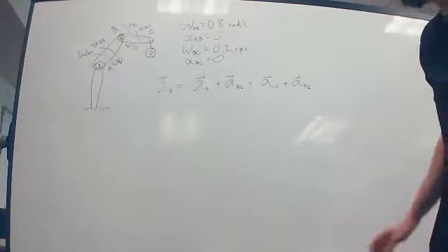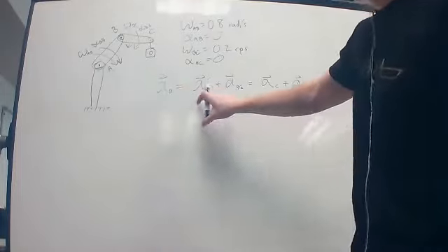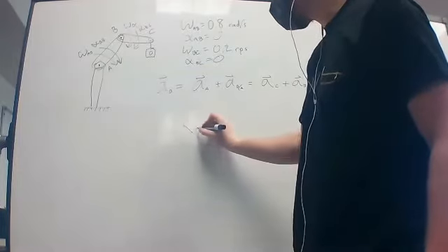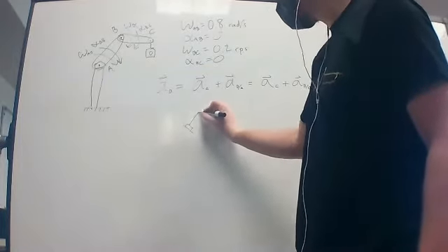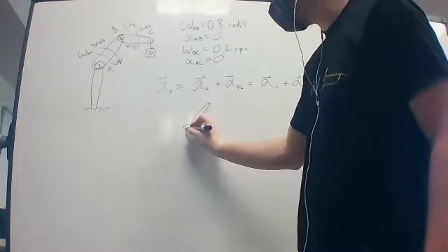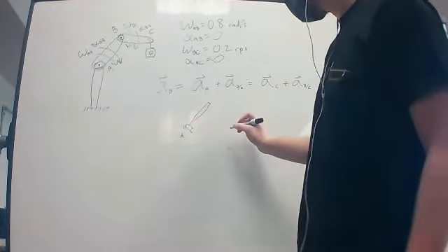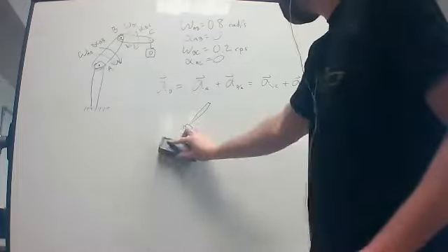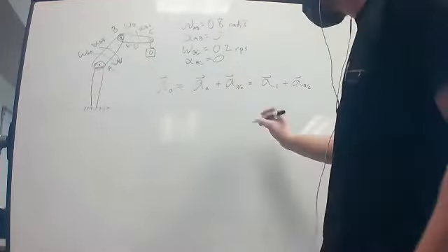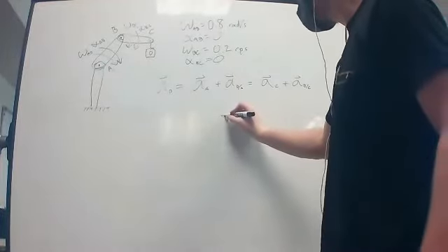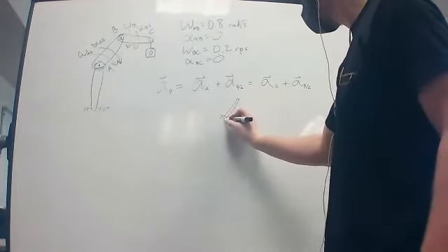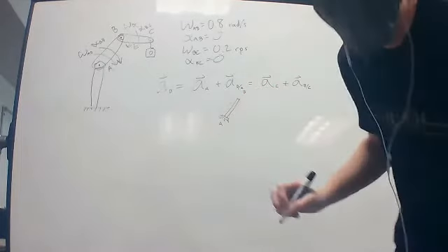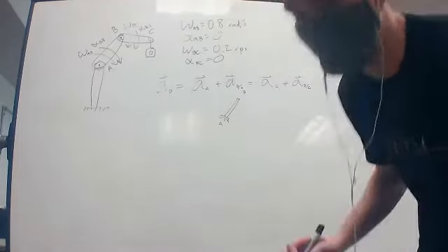So we know that point A here, we're treating AB as a rotation about a fixed point. So this is going to be a fixed point. So we're going to have something like this, with this side being A. Sorry, that should be for the B relative to A. Where this is A and our end here is B. B is going to have the acceleration tangential and normal.